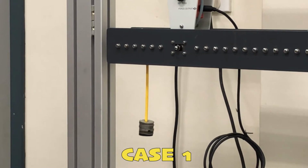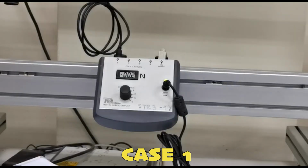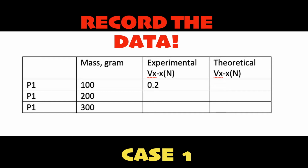The digital display recorded minus 0.02, and this must be multiplied by minus 1 to get the value of shear at the cross-section XX. The data obtained will be recorded in the data sheet and will be compared with the theoretical value later.